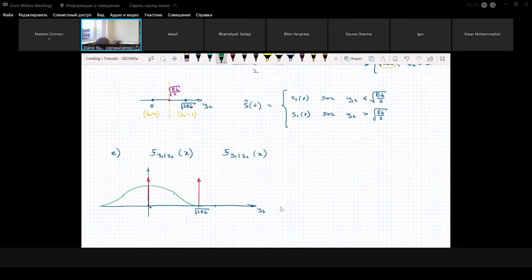So I show with this green curve a bell-shaped function that corresponds to Gaussian distribution. And this shows all possible voltages that you get when you transmit signal S1. Because when you transmit symbol S1, at the receiver side you get 0, but because of noise, you get spreading. Noise may have values positive, negative, it's all possible, and they have a specific distribution, Gaussian distribution, and then we have to plot Gaussian distribution on this diagram.